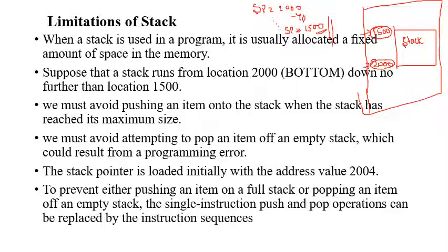What is the process when you perform the push operation? You need to reduce the stack pointer by 4. 1500 minus 4 is 1496, and this address is outside the stack, so you cannot perform the push operation.